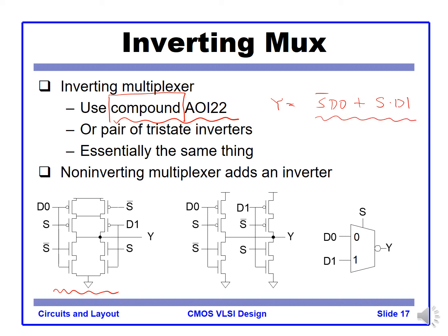So this kind of selection needs to be done, but for the CMOS circuit, we prefer to have something like that equation. Above the equation, we want to have the bar in it, because we typically implement the NMOS tree first.